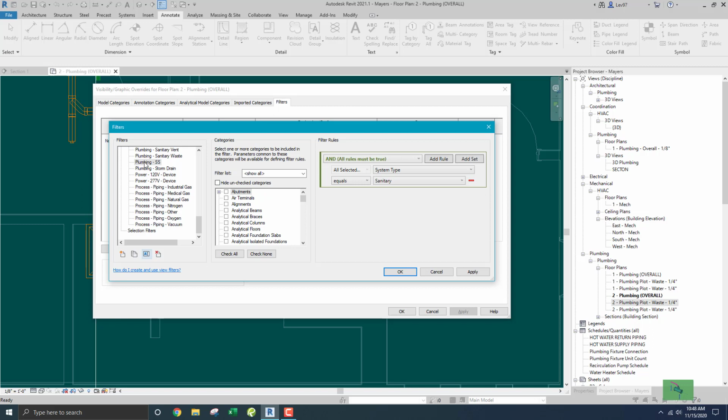I guess, well, that would be acid. There's acid waste. There's grease waste. But those two distinctions between when you're looking at just your typical bathroom waste: sanitary sewer collects if there's a water closet involved. But if there's no water closet involved, then it's sanitary waste.